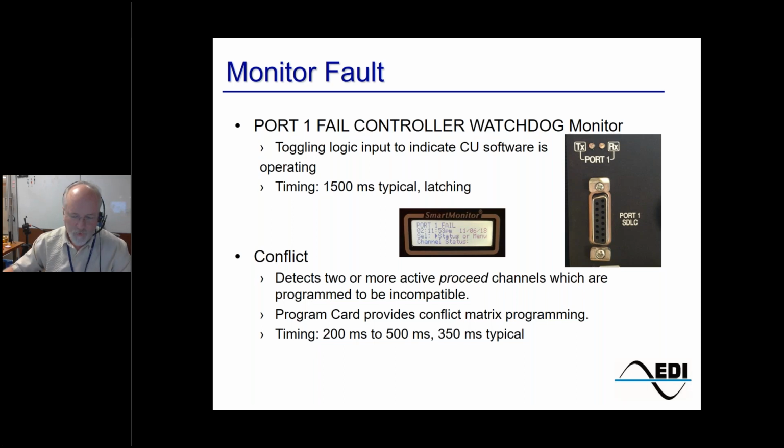So in the TS2 cabinet, one of the big problems that you'll come up with is the port 1 fault. In a TS2 cabinet, you have a communication bus, which is called the SDLC, and you want to make sure that's plugged in and working.